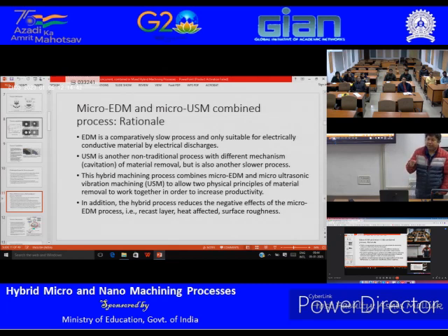Okay. Now remember, in the traditional ultrasonic machining, you don't necessarily use dielectric, okay? You use some other fluid that is mostly purely water, so that water creates lots of vapors, and that helps in the cavitation. So your target is to select a fluid that will facilitate the cavitation, right?